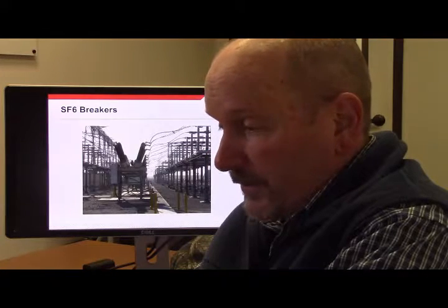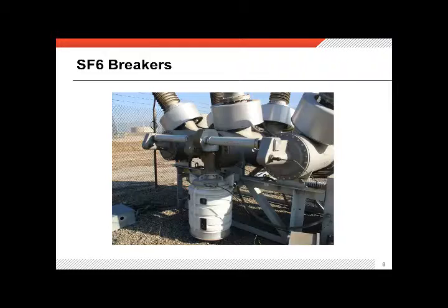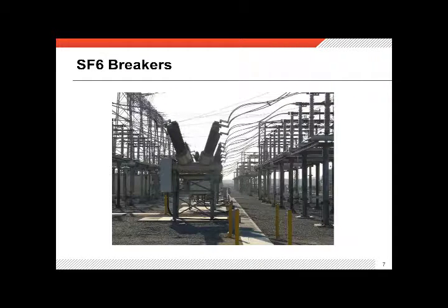Anyhow, I think it's rather ingenious, and just one of those little things that all of our clients have, different things that are important to them in their designs. Anyhow, the way circuit breakers like this work is there's a mechanical connection between the 3 poles. There's actually a bar that connects them, and then somewhere within that mechanism there's a spring.